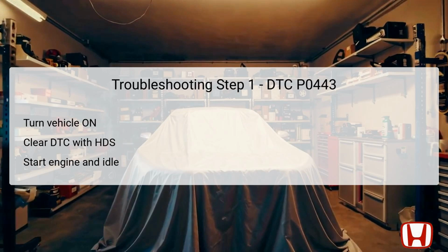The initial step in troubleshooting DTC P0443 begins by turning the vehicle to the on position, which prepares the electronic systems for diagnostics. It is important to clear the DTC using the Honda Diagnostic System, or HDS, to allow for a fresh evaluation of the vehicle's status.